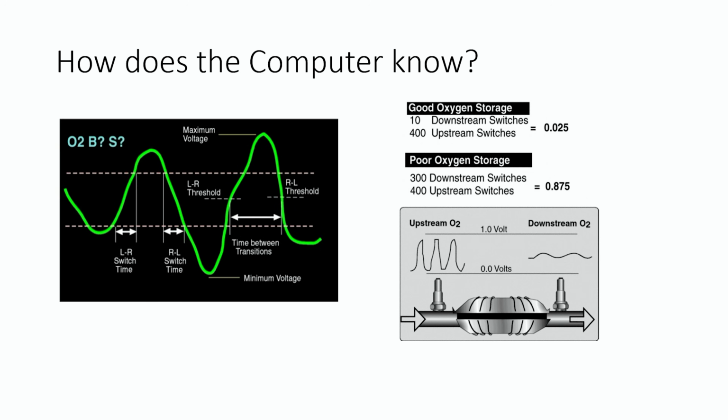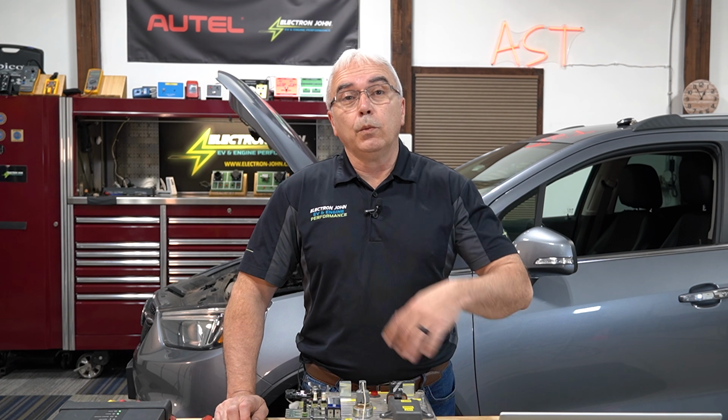And we also have the catalyst sensor. So in OBD2, in order to set a P0420 or P0430 code, in essence what we're doing is comparing the amplitude and the frequency of the pre-cat and post-cat O2 sensor waveforms. As long as the post-cat is not 30% or more of the pre-cat O2 sensor, we won't set a 420 or 430 type of trouble code.